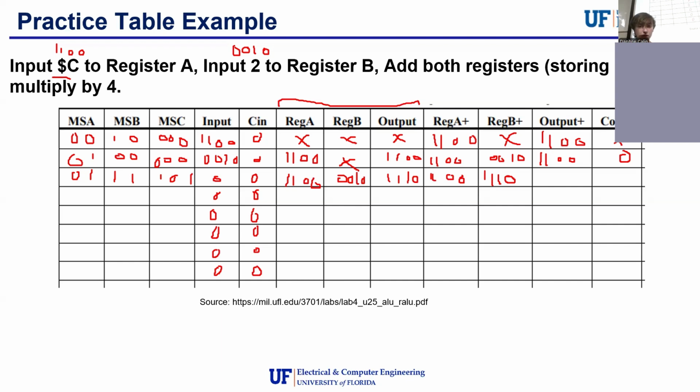And the output, we would add again these numbers. So the 0 and the 0 would add to be a 0. The 1 and the 0 in the second position would be a 1. Now, when adding two ones, if I do 1 plus 1 in binary, we get 1, 0 because this is 2. And if we add 3 ones, you can think of adding these two right here as being 1, 0. And then we add in the third bit to this number, and we get a 1, 1.